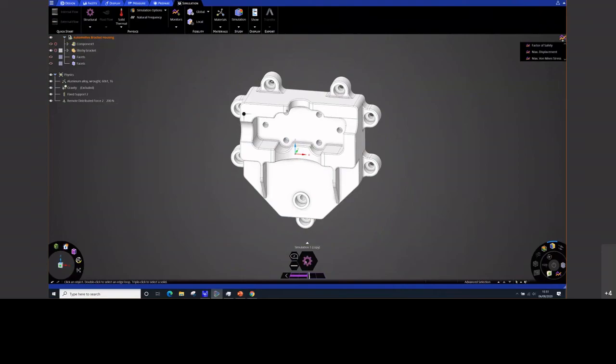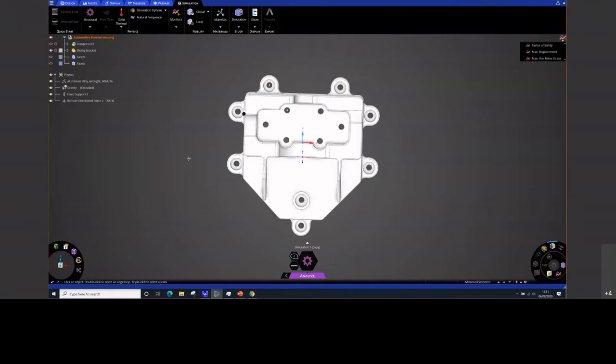But in the analyze stage, you will be able to fully define the model and mesh it, and you can set global mesh settings or local mesh settings to mesh it how you wish. You can then get what we call higher fidelity results, or double check your results in a more advanced simulation. That's pretty much the demo.